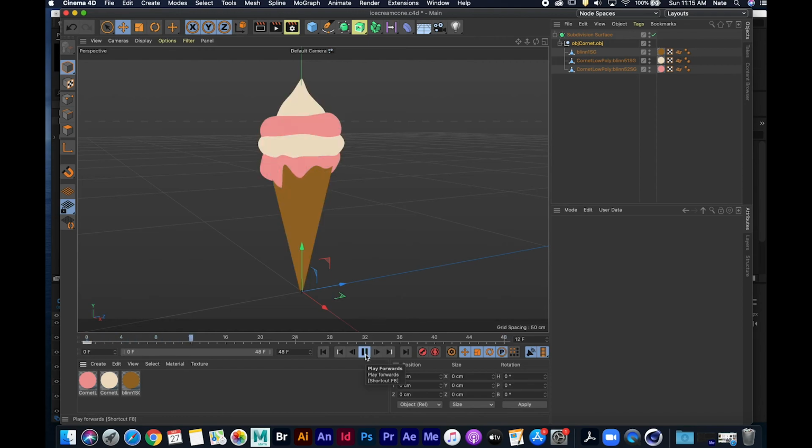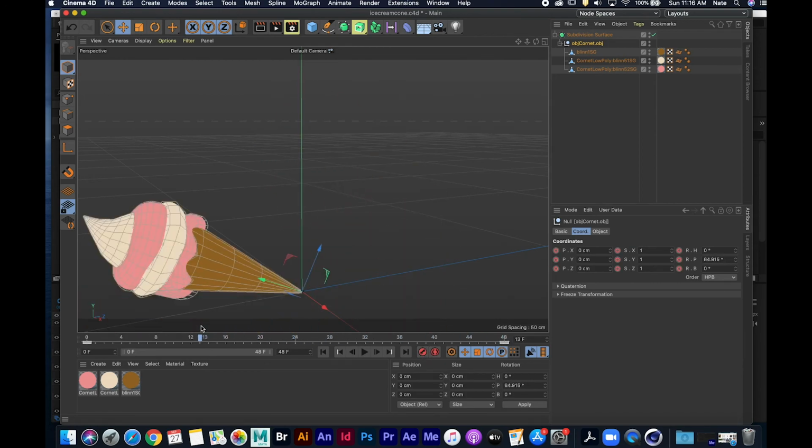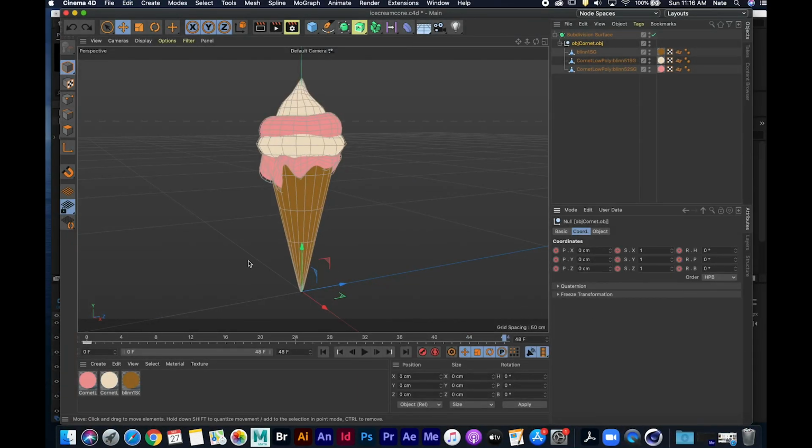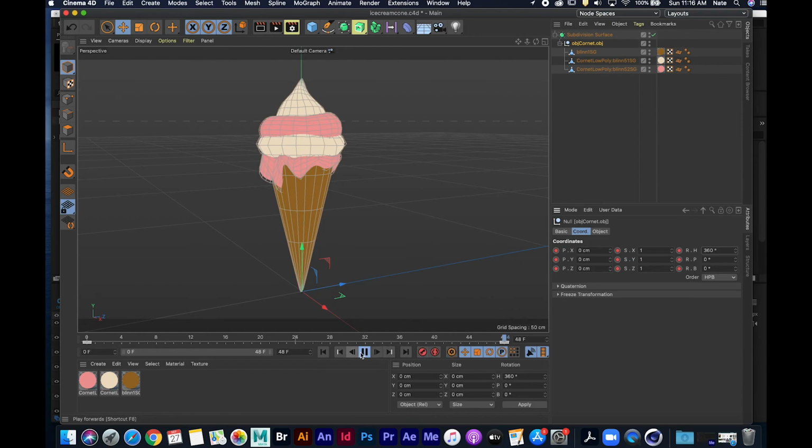And now if I hit play, oh, nothing happens because I forgot to hit my keyframe. So select my object again, go back here, it didn't change, so 360. Now I want to make another keyframe, I'll add that there. That's not the movement I wanted. I wanted it to turn around, so which one does that? There we go. So I'll add my 360 here. Make a keyframe. Now let's play. Great, it's spinning, it's rotating, that's what we want.